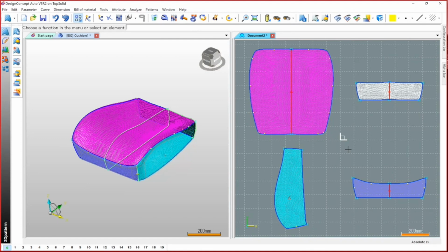If the triangle size is small, it takes more time to complete the flattening process. The fast mode prioritizes the lengths of the parts. But standard mode prioritizes the area. I mean the space. You know what I mean?